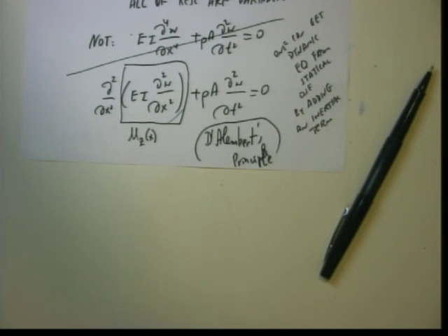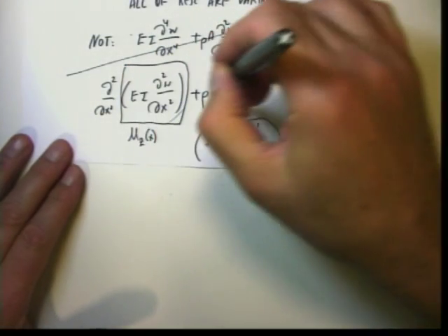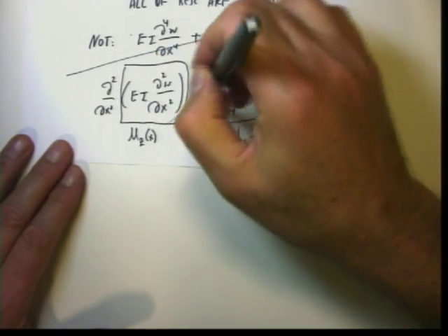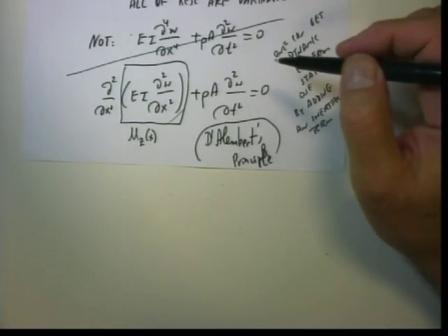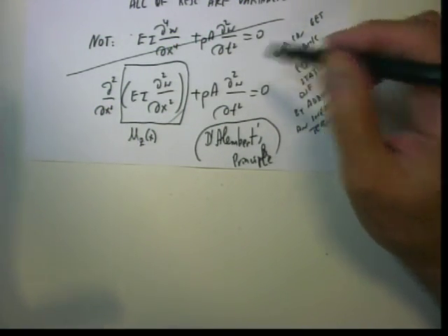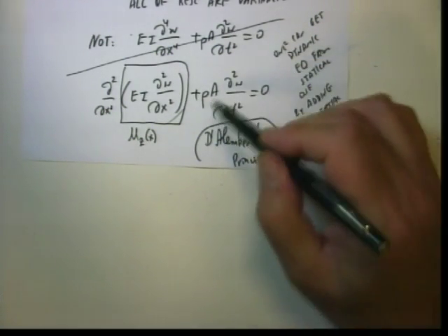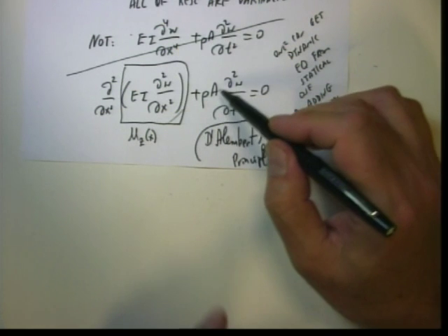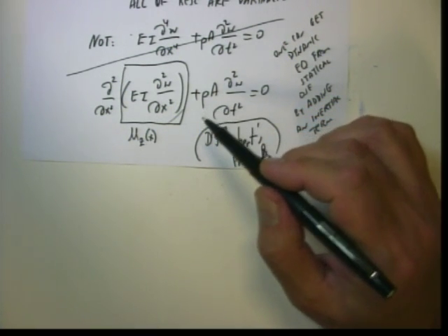Now, one can actually prove that this particular expression is correct by obtaining the vibration equation for the beam by something called Hamilton's principle. But then we will obtain this term. But why adding this term a priori is correct, we cannot prove. It just turns out to be right. Any questions?